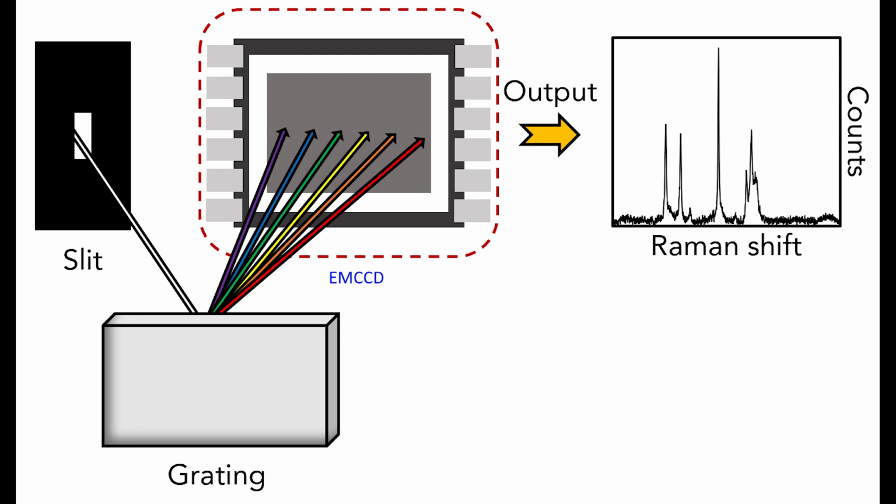An EMCCD, electron multiplying CCD, is a special type of CCD sensor that is designed to be more sensitive to light compared to a regular CCD. This increased sensitivity is achieved by using a special amplification circuit that multiplies the charges generated by pixels. EMCCD cameras are often used in applications where low light levels or high sensitivity is required, such as deep space astronomy.